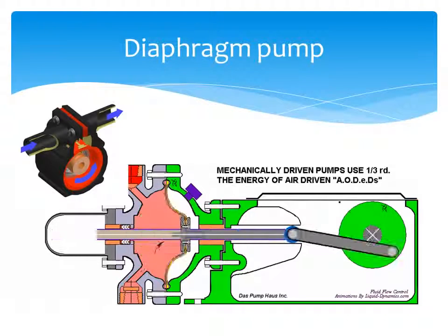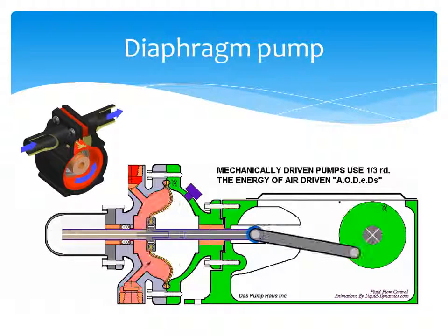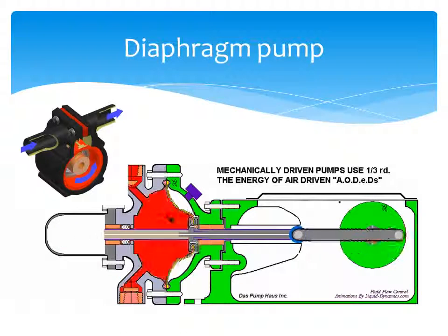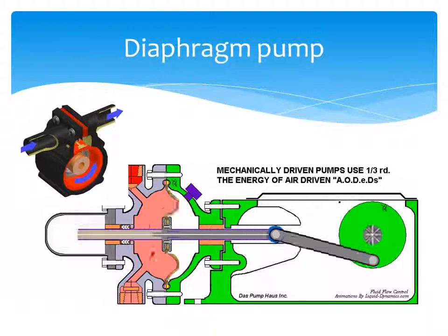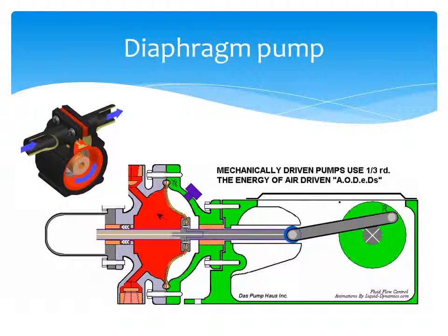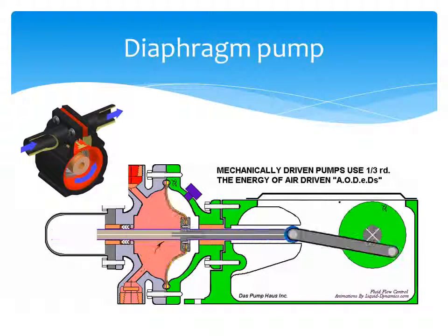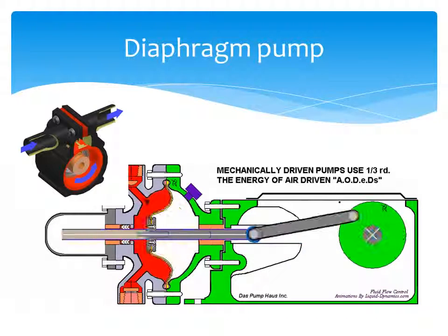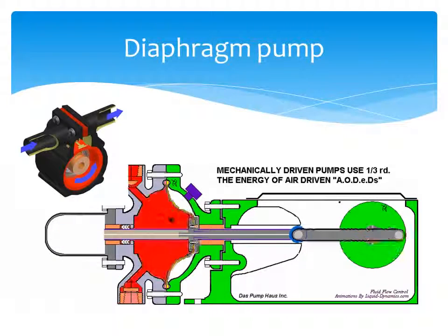A diaphragm pump or pneumatic diaphragm pump uses a combination of the reciprocating action of a rubber, thermoplastic or Teflon diaphragm and suitable valves either side of the diaphragm to pump a fluid. When the volume of a chamber of either type of pump is increased, the diaphragm moving up, the pressure decreases, and fluid is drawn into the chamber.